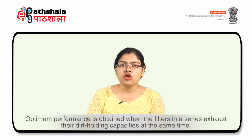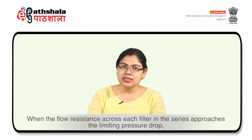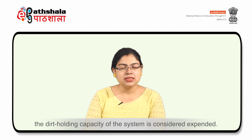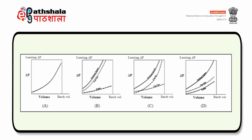Optimum performance is obtained when the filters in a series exhaust their dirt holding capacities at the same time. When the flow resistance across each filter in the series approaches the limiting pressure drop, the dirt holding capacity of the system is considered expended. Figure from A to D, as shown on the screen, shows the pre-filters with adequate and inadequate dirt holding capacity.